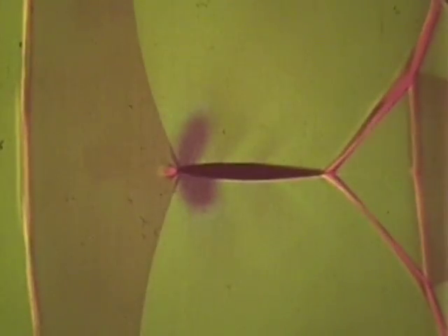As before, the supersonic regions are lighter green. Like the shock waves on the wing, the bow wave is formed by the constant piling up of pressure waves, this time from points near the leading edge inside the subsonic region.